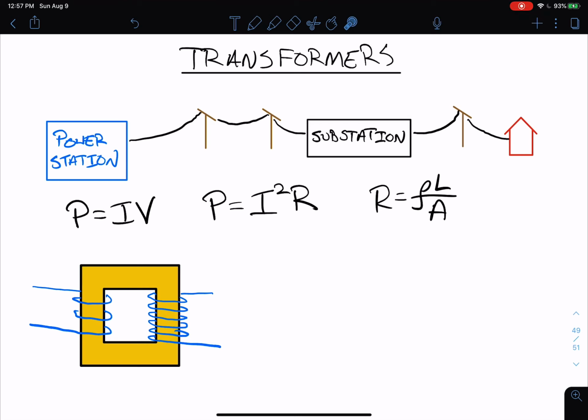That's why we're using a magnetic material, so that the field travels through the iron, or I should say, so that it passes through this secondary group of coils, of loops. Now, if you're using a constant DC, then these loops are just going to see a constant flux. Nothing interesting is going to happen.